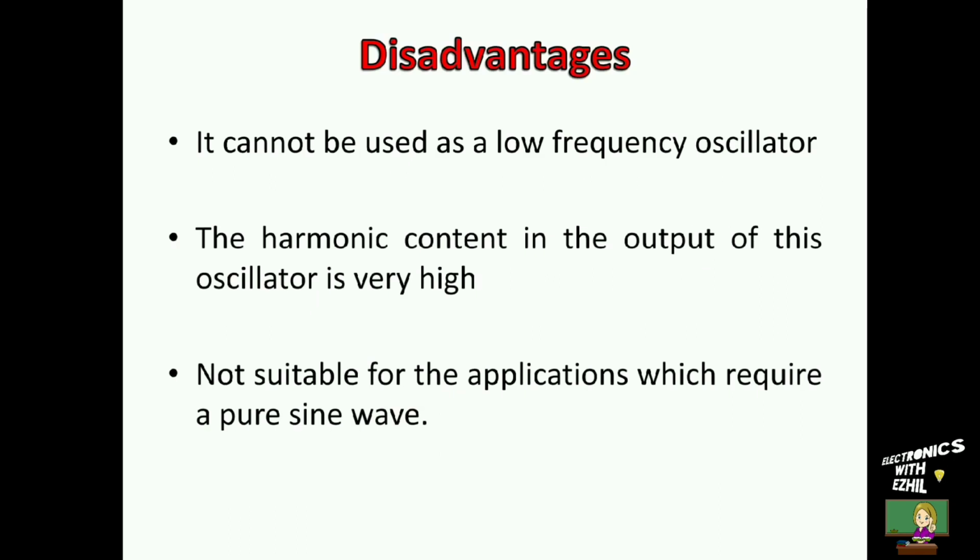Disadvantages. It cannot be used as a low frequency oscillator because high value of inductors are not possible practically. The harmonic content in the output of this oscillator is very high. So it is not suitable for the applications which require a pure sine wave.